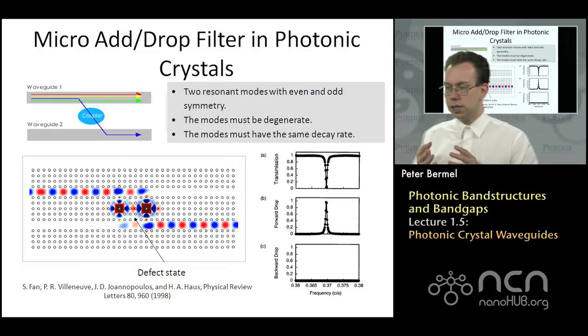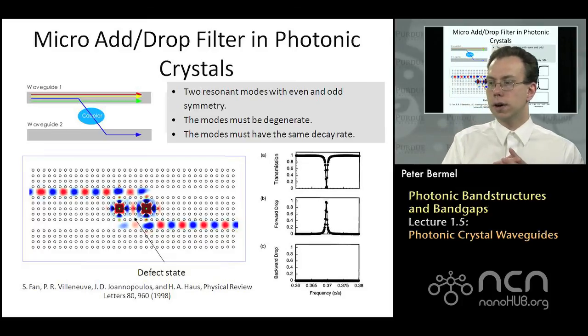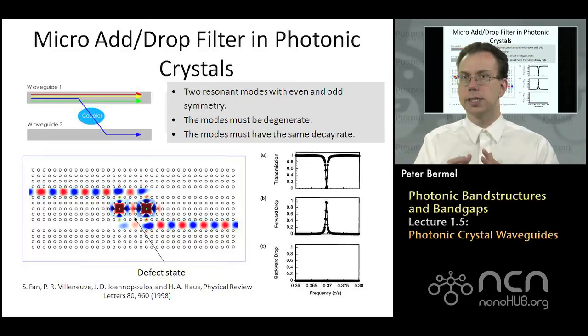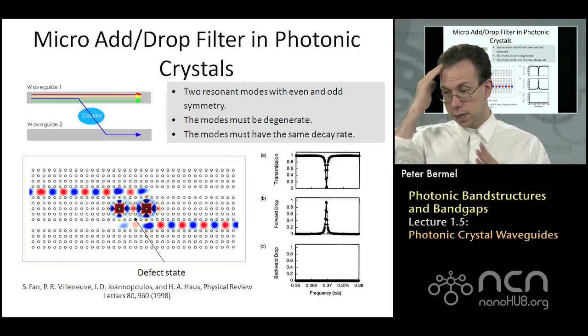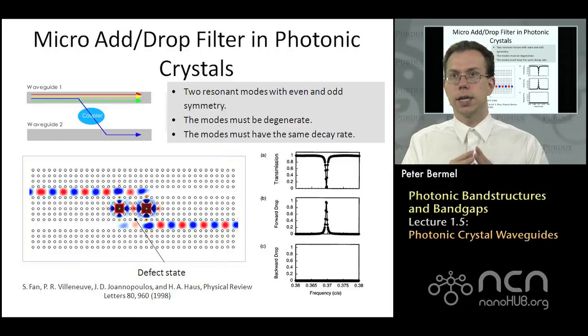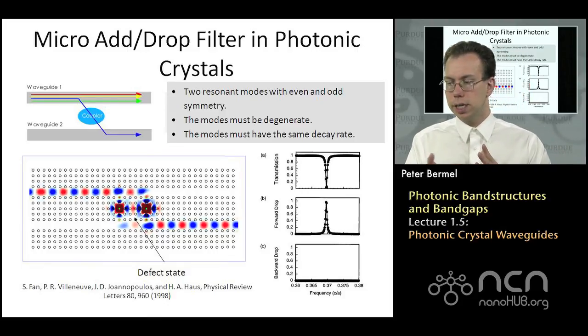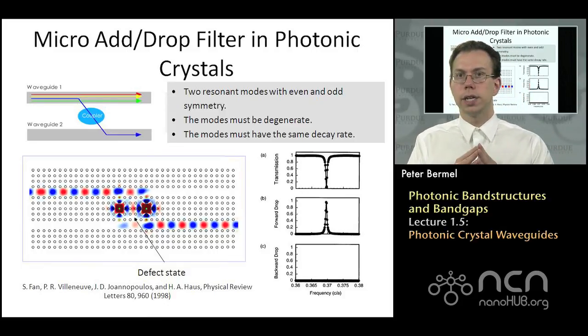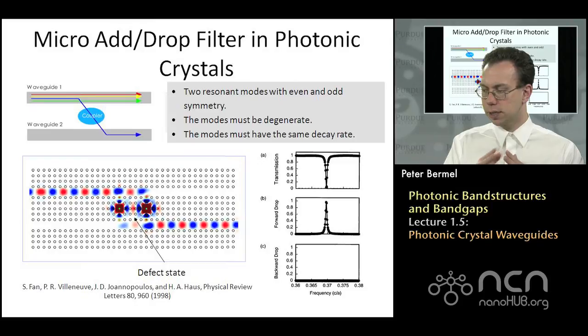And so the idea is that these two resonators interact so that the coupling only happens at a very specific wavelength which you're interested in, which also could be thought of as a very high quality factor mode state. So if you had low quality factor, you couldn't even dream of doing something like this. And there are potential applications for this sort of technique, both in telecommunications, like for dense wavelength division multiplexing, for example, and also applications in terms of optical comb generation and many other things where you need to have a fine discrimination between nearby wavelengths.